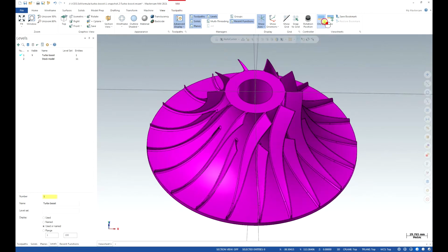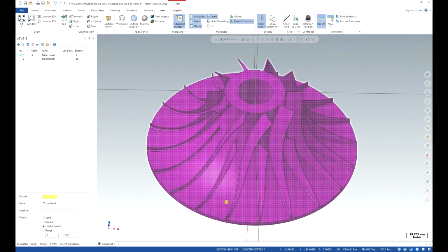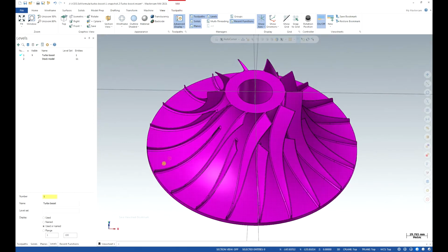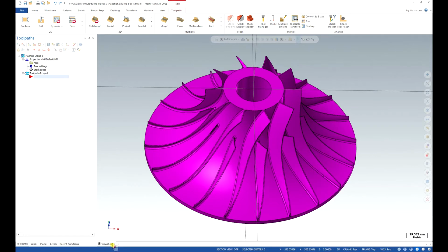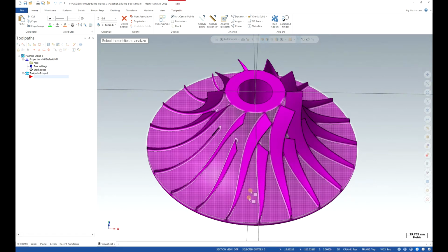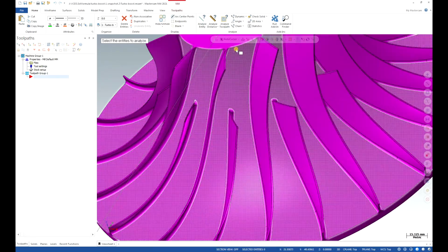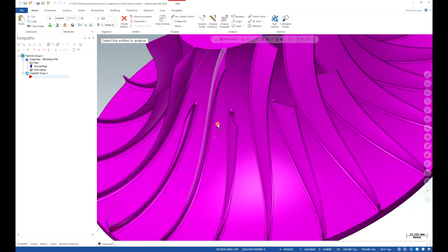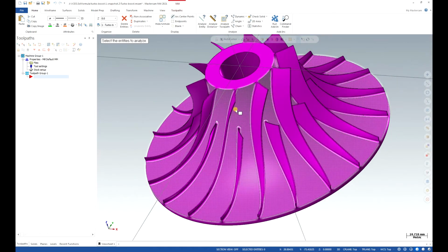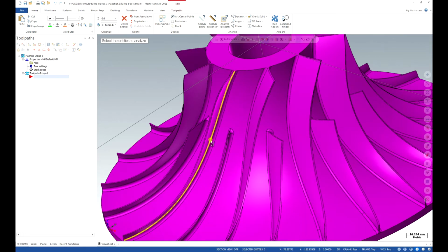It will let me go back quickly to the same position so I can work and see my programmed two blades and the same section. As you can see, the whole floor of the impeller is created as a single face. I will split that face and work only on the small portion just between the long blades, and then I will translate it around to finish the whole floor.